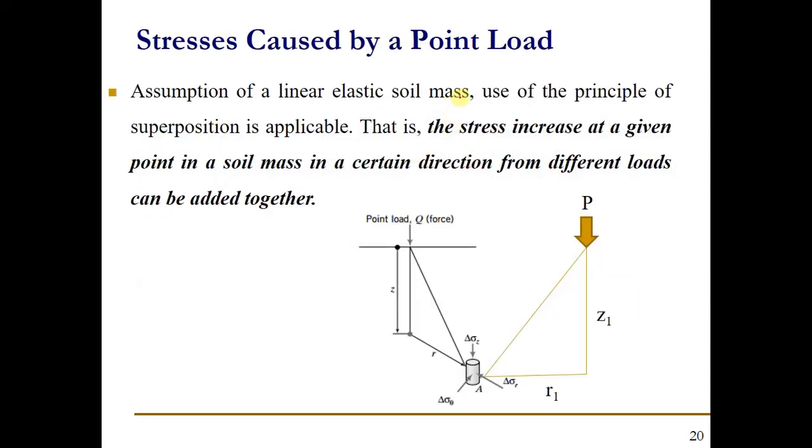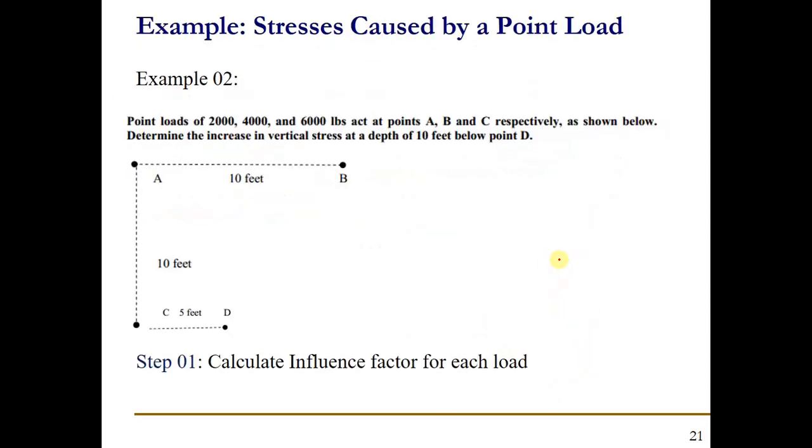Assumption of a linear elastic mass. Use of the principle of superposition is applicable here when we are dealing with two point loads, point load 1 and point load 2. Now, what is the principle of superposition? That the stress increase at a given point in a soil mass in a certain direction from different loads can be added together. So here we need to find out the delta sigma due to these two point loads.